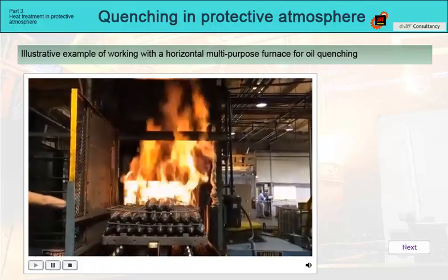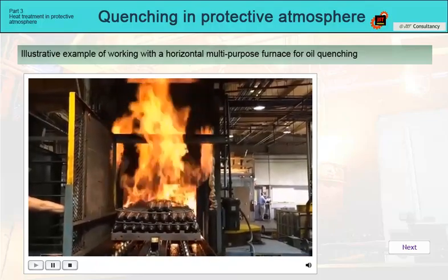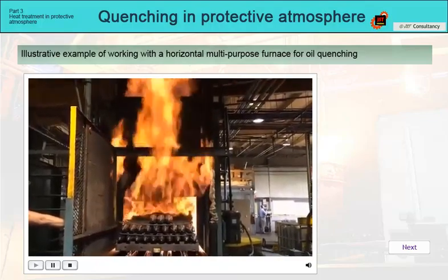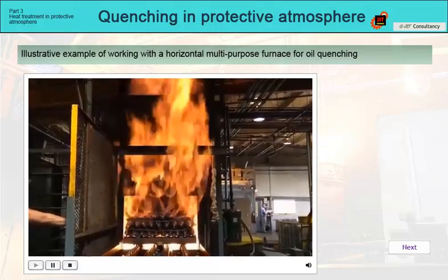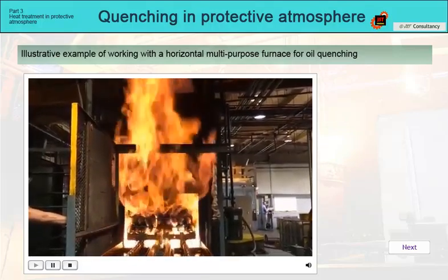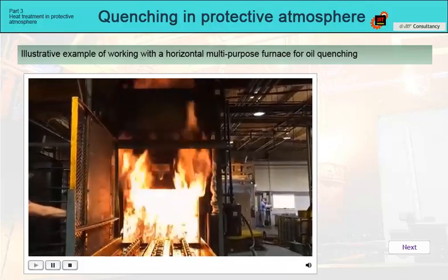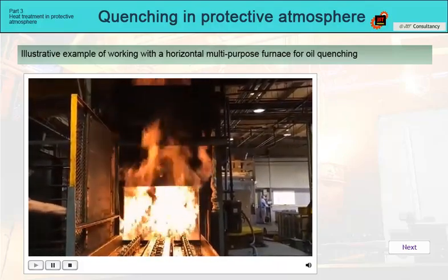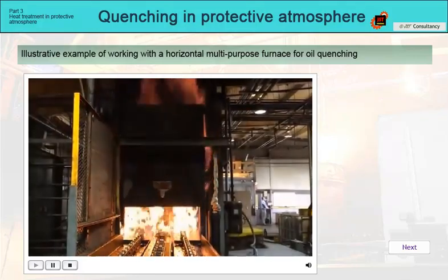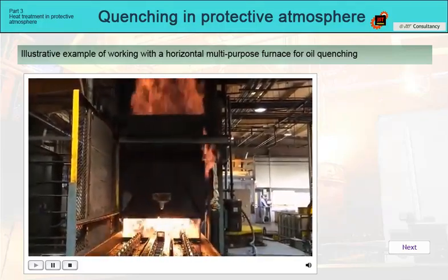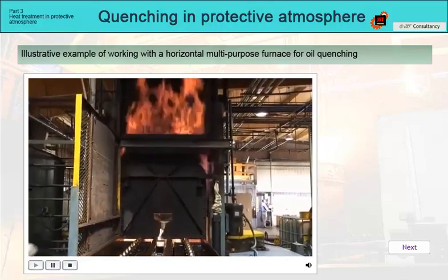The unloading door opens, and the batch goes into the cold chamber through a flame screen. It is ignited by the safety burners at the bottom of the door when the door opens slightly and the endo-atmosphere begins to penetrate outside the furnace. This guarantees safety against a possible explosion and prevents air from entering the furnace. Once the batch is in the furnace, the door closes and the actual process begins.